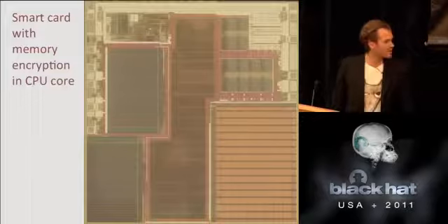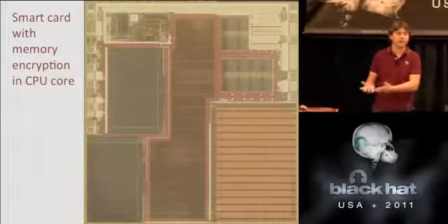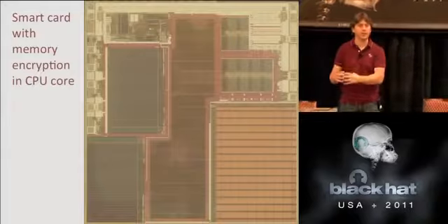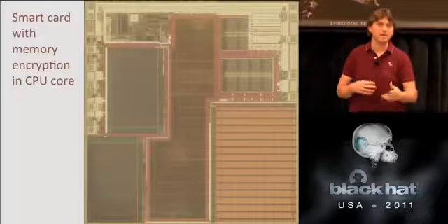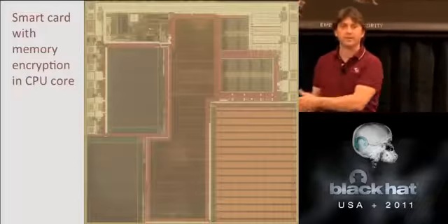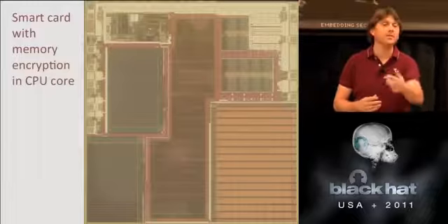But it all begins with tracing from the ROM output, let's say, because you know the chip runs from ROM on power up. They always will. They have to. It's the only static block of code there. So follow your ROM outputs. You sit on them with needles. I mix techniques. So I'm mixing what Carsten's talking about today with my other known techniques. So it all depends, but we can discuss it after.